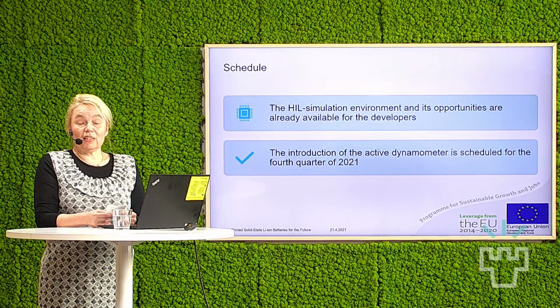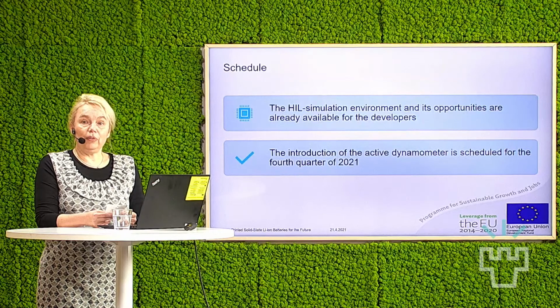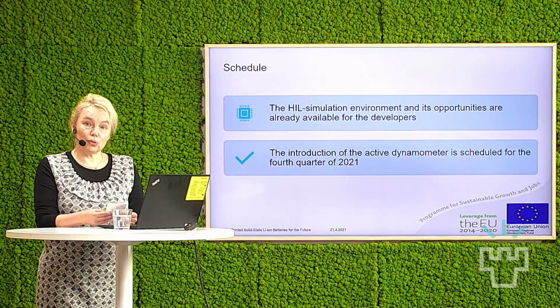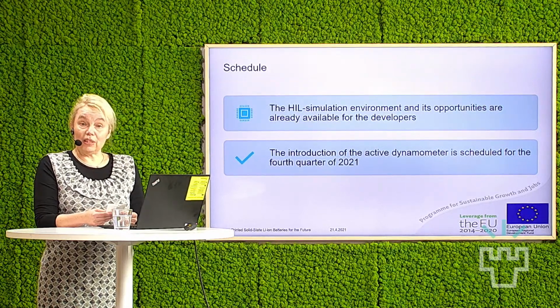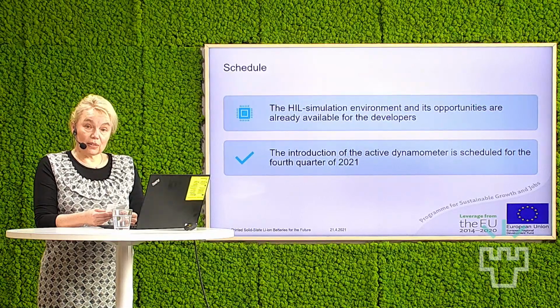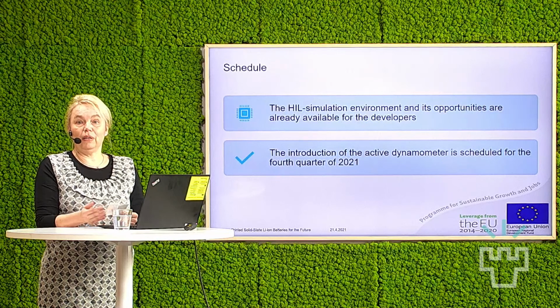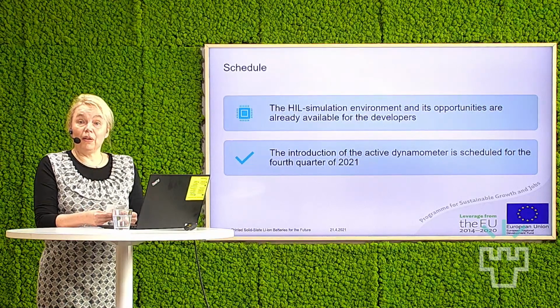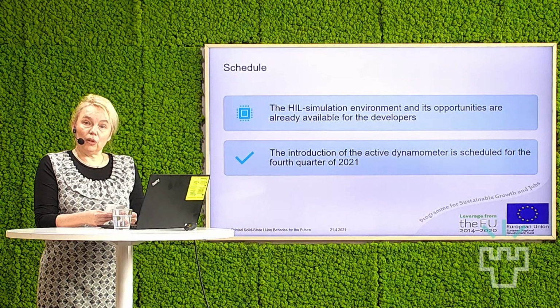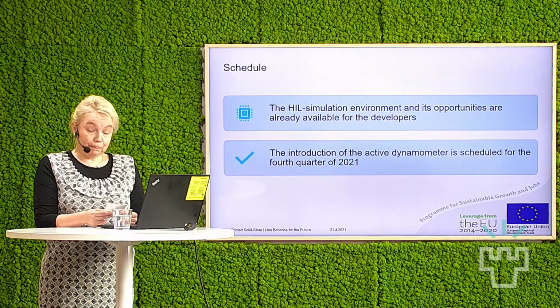These anode materials we have already tested for screen printing, and we have compared them to doctor blade coating, and I can say that we already have a solution, and the behavior is equal to what we have in the existing commercial battery cells. And in the future, metallic lithium foil would be one good option if we coated it. That is also one reason why we are collaborating with one of the international research units.